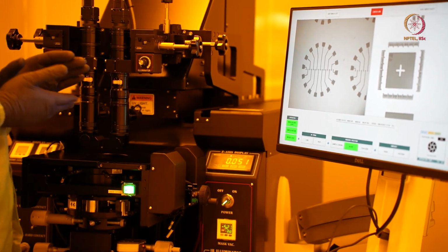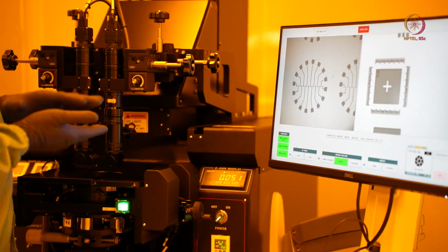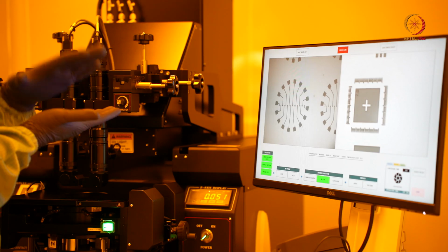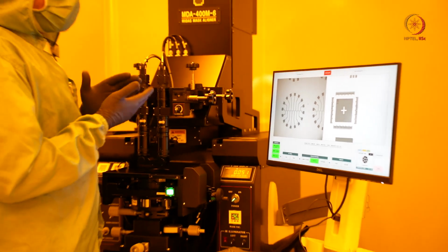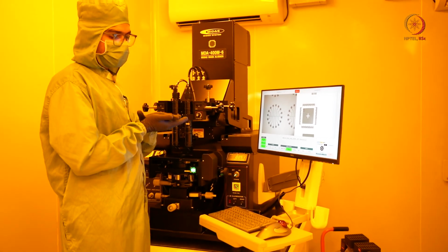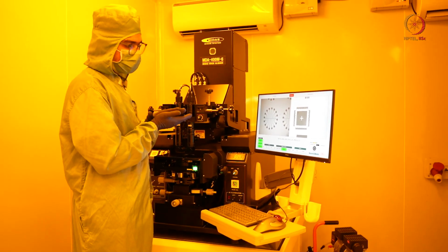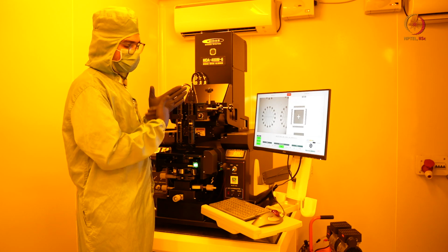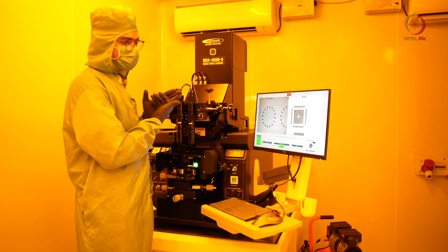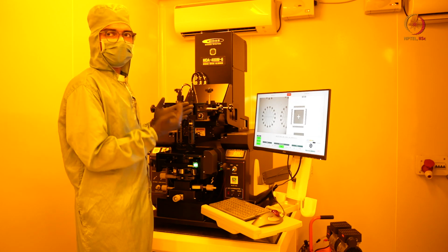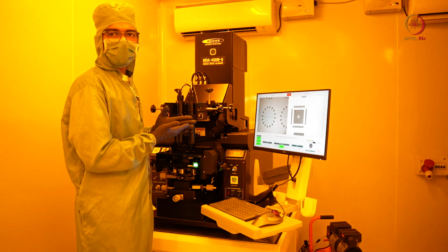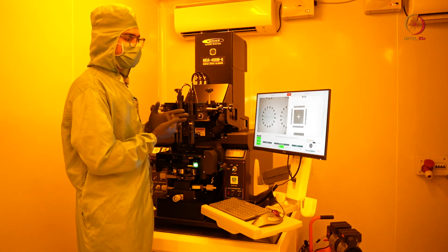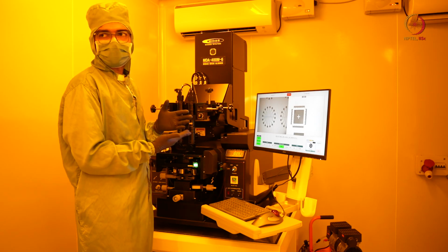So this is known as proximity lithography, where you don't really have to have the mask and wafer in contact. The reason to give a gap between the mask and the wafer is that the small gap will prevent any photoresist from remaining on the mask surface. So we can have longevity in the mask life. And then there are other optical properties which are out of the scope of this lecture.